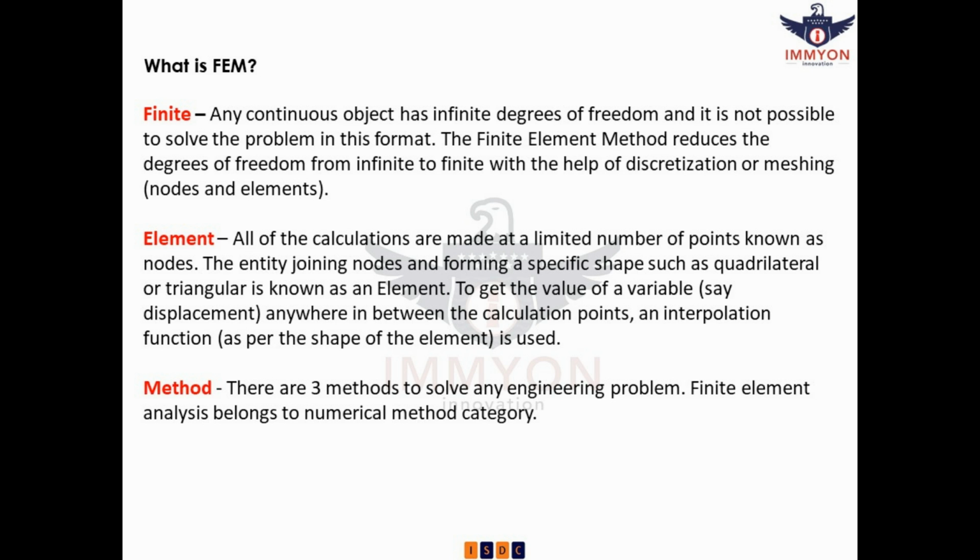Element means all of the calculations are made at a limited number of points known as nodes. The entity joining nodes, and forming a specific shape, such as quadrilateral or triangular, is known as an element. To get the value of a variable, say displacement, anywhere in between the calculation points, an interpolation function, as per the shape of the element, is used.